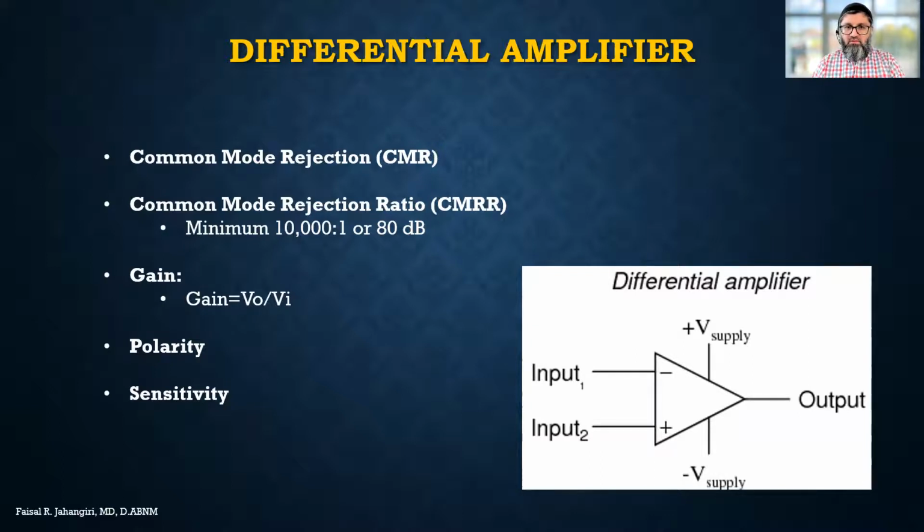If it is negative, it becomes positive; if positive, it becomes negative. So if there is a signal of minus 2 microvolts coming into the active input, and a signal of 2 microvolts coming into the positive input, the minus 2 becomes positive 2. So it will be 2 plus 2, which is plus 4. So it will be a 4 microvolt signal going upward on the screen.